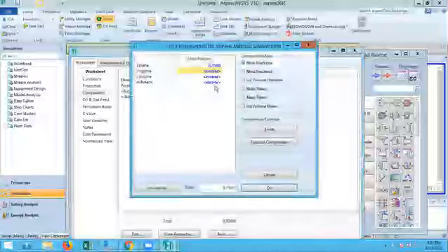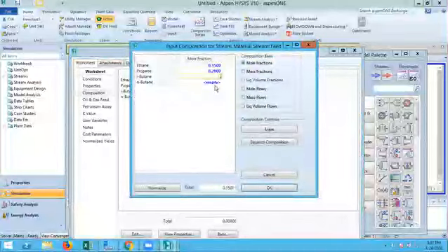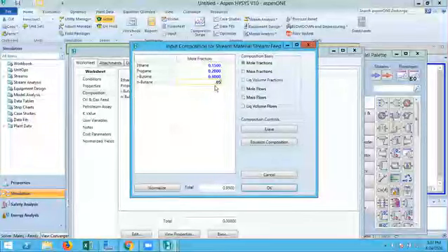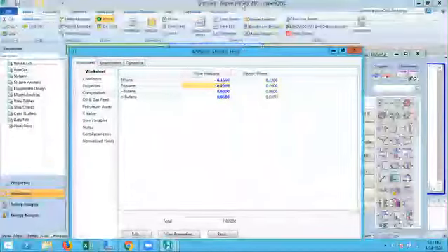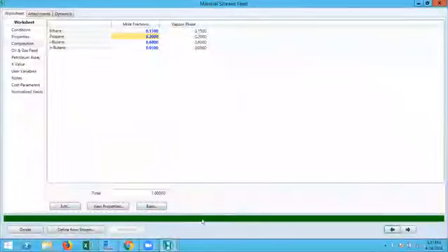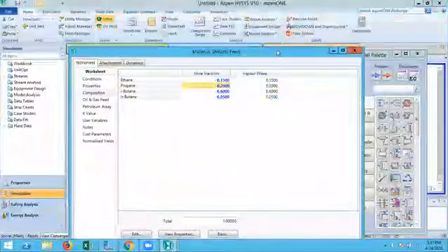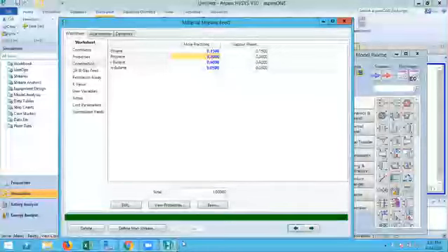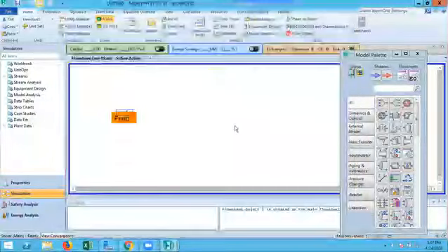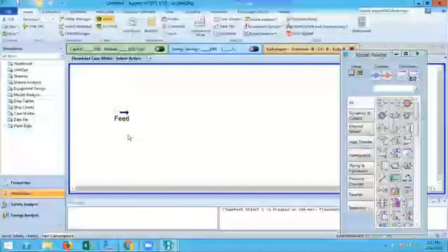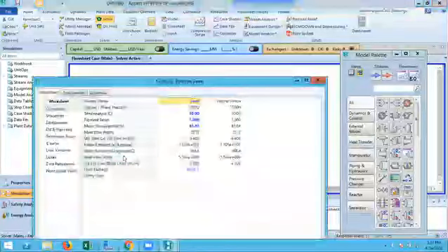The propane is 0.2, and this one 0.6. And finally, the normal butane 0.05. And you will see that they add here to 1. Now, once I press OK, you will see that this stream now is converged. You can see that green line that tells you that everything here is OK now. So now you can close this, and that completely defines your stream.